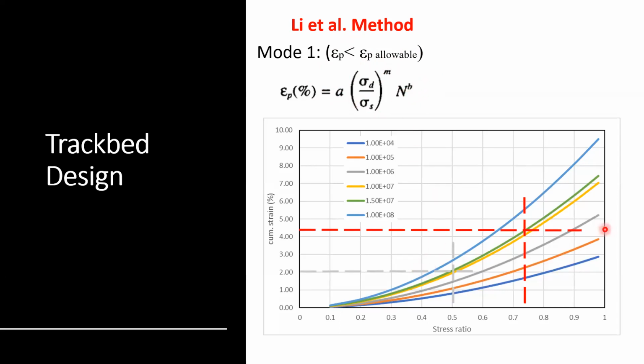And then you see here with the stress ratio, you have a cumulative strain, right? This is basically a soil that's yielding, right? As we go with higher stress ratio close to 1, you're basically reaching the maximum capacity of your soil. You're getting a very high plastic strain, and you can say, okay, if I am comfortable with a stress ratio